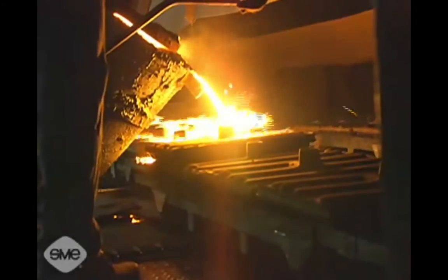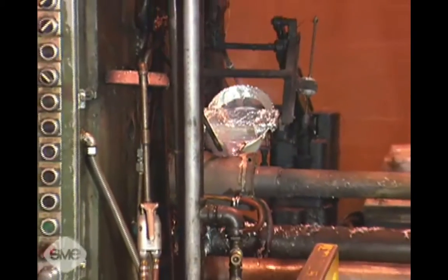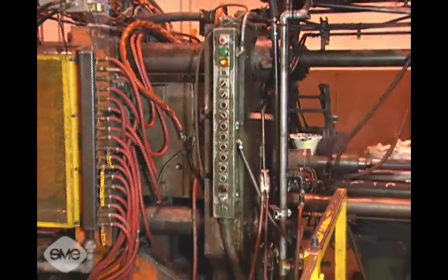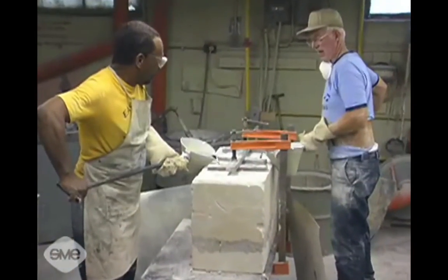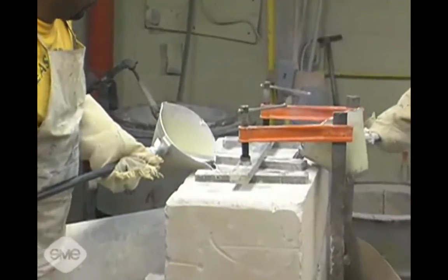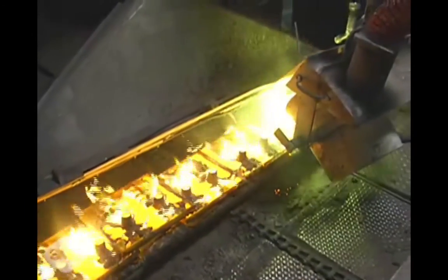Casting is the solidification of molten metal that is poured into a mold or injected into a die having a cavity in the shape of the desired part. Casting is used in virtually every industry, since all metals can be cast. Even mill forms, such as bar and plate, are produced from cast metal. Casting is usually the quickest way to shape metal into a part. Because of this, casting is used both for prototyping as well as production of large quantity parts.